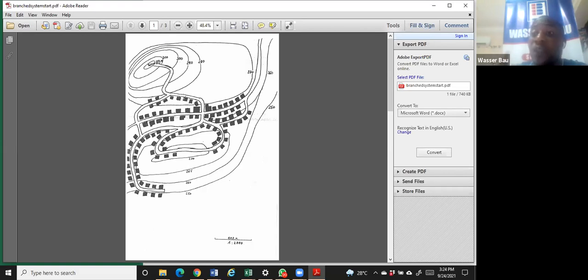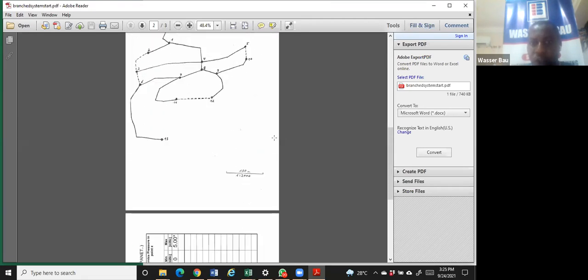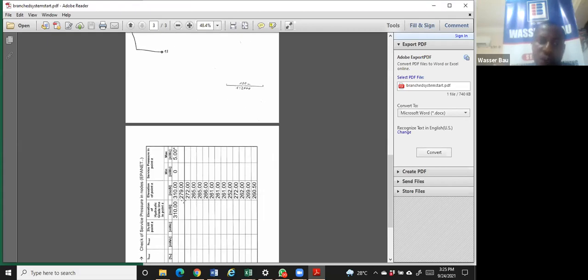But a good surveyor will give you this information in Excel. If you're an infrastructure person, you know that the surveyor will give you the result in Excel format: the points, X coordinates, Y coordinates, elevation, and maybe the description. Or the longitude, the latitude, the elevation, the description, whatever format he uses. So this can come from the surveyor. But if you have a layout like this, you can also read it out. You can see this point is 280 something. If you go to my drawing, you see that it is at 279. 279 and 280 are almost the same thing.